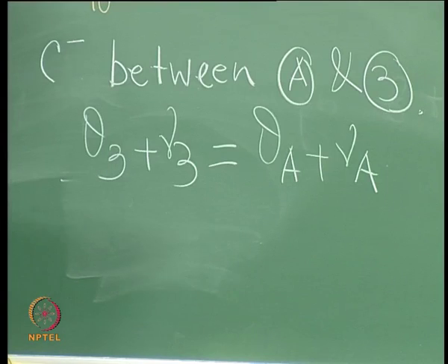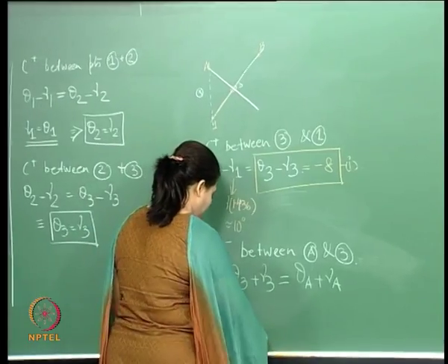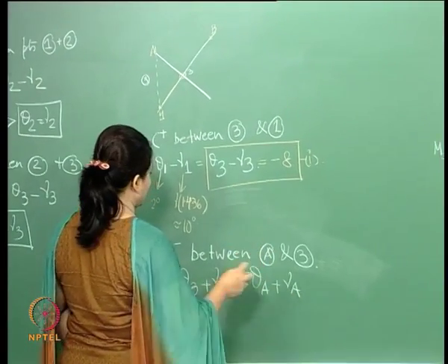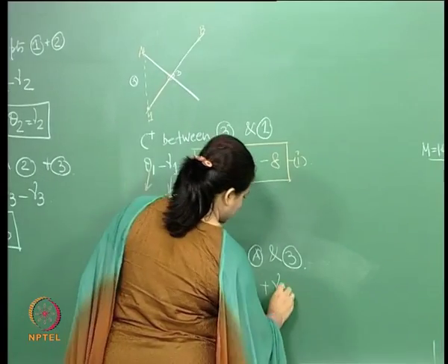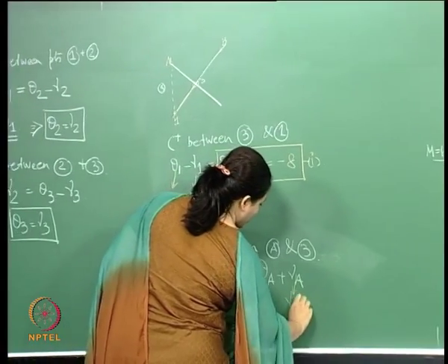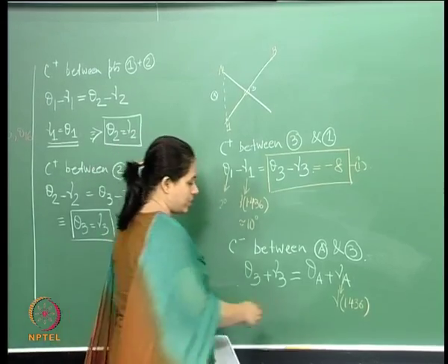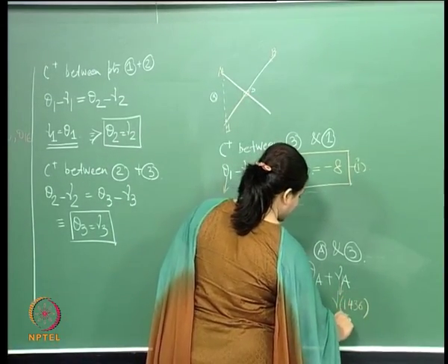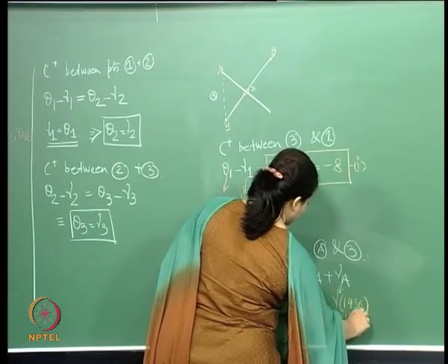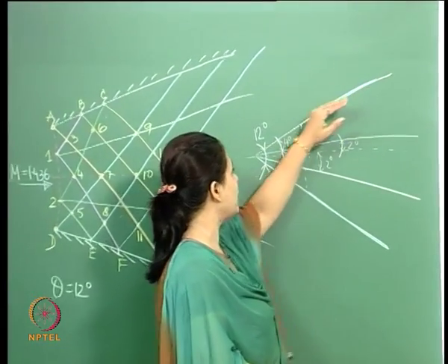Right. So now if I have this, what is theta A and what is mu A? Mu A is again this. So mu A out here is again mu 1.436, isn't it? Because this is also at the inlet, this is also equal to the Prandtl function corresponding to 1.436, and this is again around 10 degrees. And theta A, what we saw from here, is my wall out here.